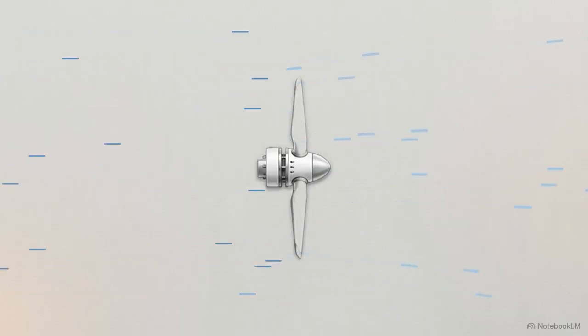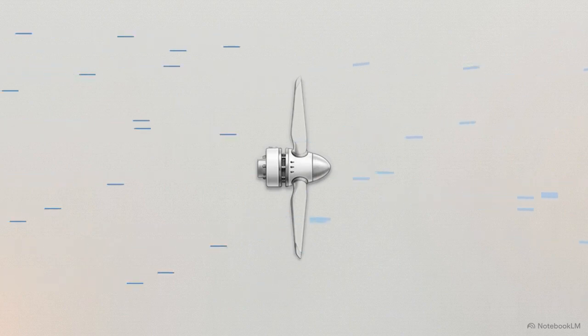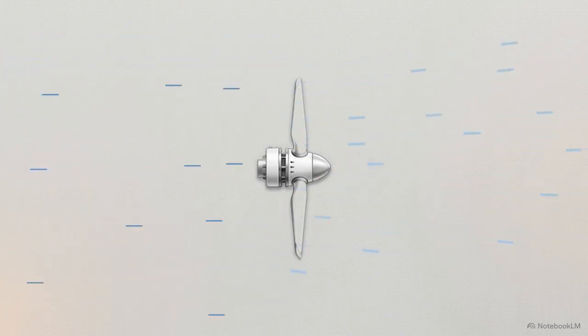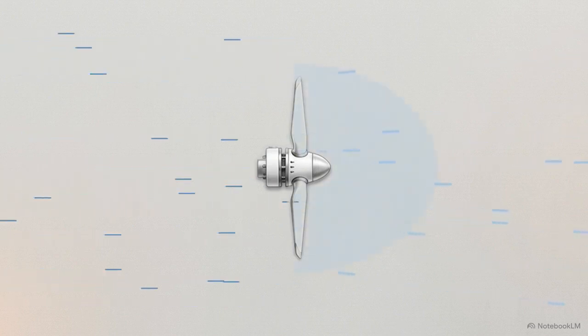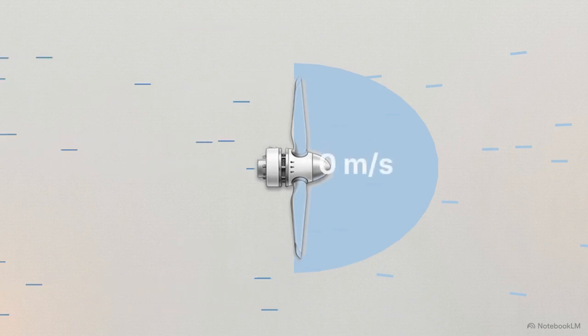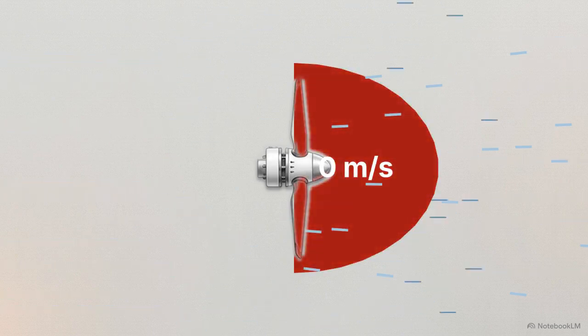Energy extraction is governed by a fundamental fluid dynamics constraint. For a turbine to capture kinetic energy, it must physically slow the air down. If a turbine were hypothetically 100% efficient, it would extract every joule of energy, causing the air velocity behind the rotor to drop to exactly zero. Such efficiency is physically impossible. If the air coming out the back stops moving, it creates a blockage that prevents any fresh wind from entering the turbine in the first place.